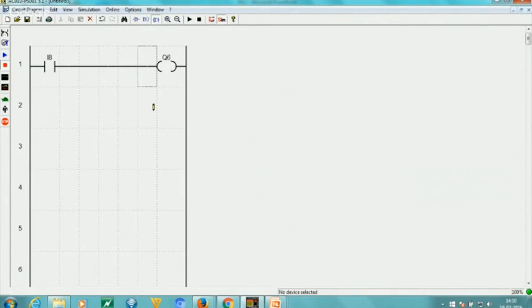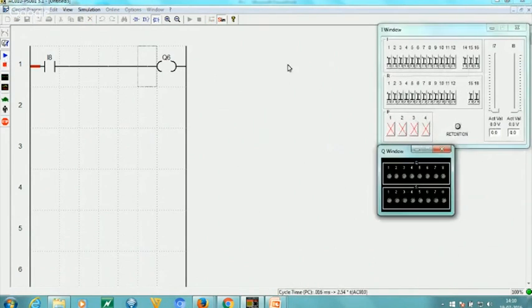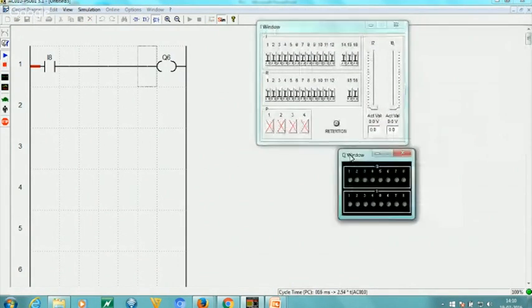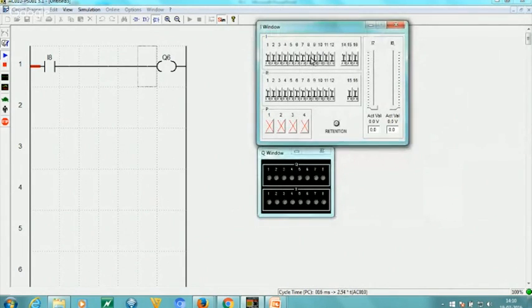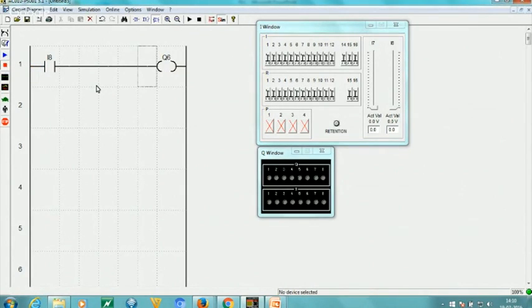Now again, this is the simplest program. With I8, we start Q6 or stop Q6. You close I8, the Q6 runs. You open I8, Q6 stops. Now, what if we want the Q6 to work when we receive a momentary input or an impulse from I8, and after that, even if the input is gone, the Q6 may keep on running?